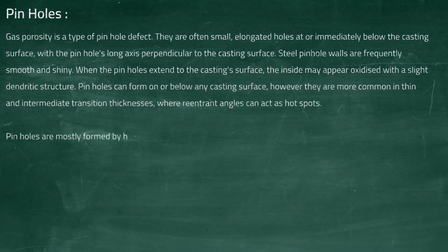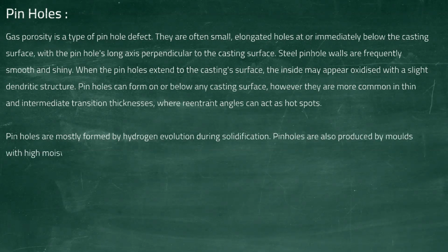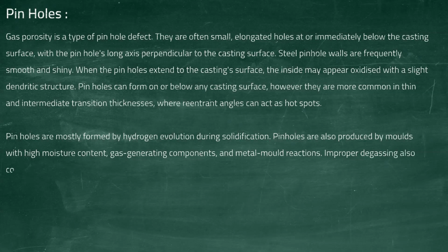Pinholes are mostly formed by hydrogen evolution during solidification. Pinholes are also produced by molds with high moisture content, gas-generating components, and metal mold reactions. Improper degassing also contributes to gas porosity.